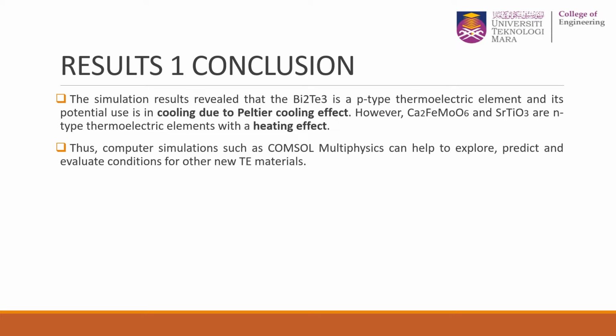For the conclusion, the simulation result revealed that bismuth telluride acts as a p-type thermoelectric element and potentially used as a Peltier cooling effect. However, both the perovskite material act as an N-type thermoelectric element with a heating effect. Thus, computer simulation, such as COMSOL Multiphysics software, can help to explore, predict, and evaluate conditions for other new